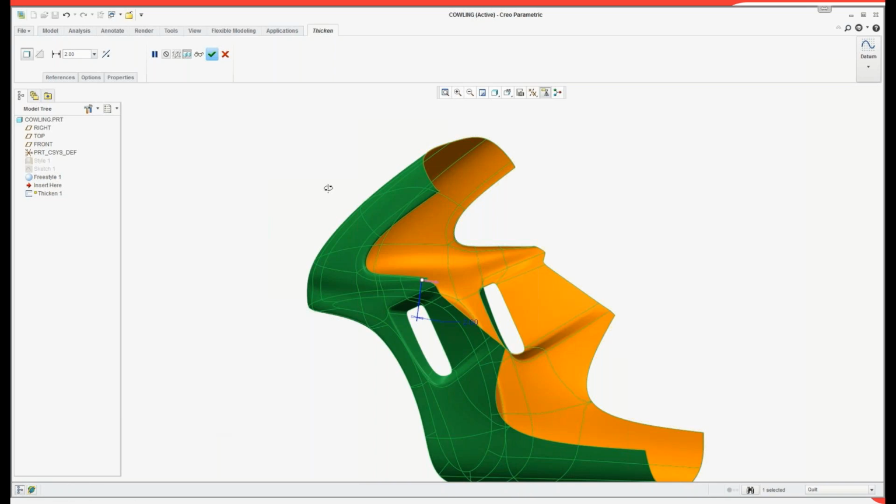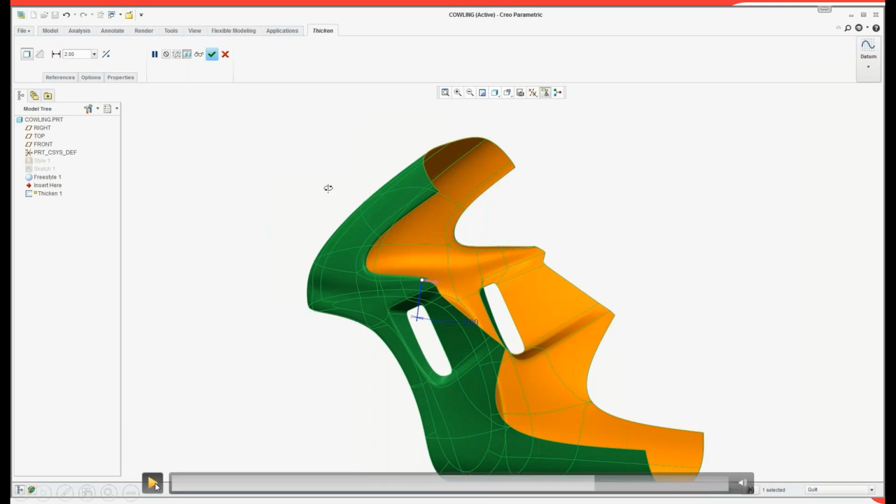Also, if you have completed that styling or concept, and it is assembled in the final assembly, if any problem arises, maybe it is interfering with other components, of course you can modify it or add details to the component, which is basically outside that styling environment. So you can keep adding other features which are not part of this styling, and you can make that component a functional component. And any changes you want to make, you just go to that particular Freestyle environment and you can make changes at any point of time. So this is how the complete environment works.